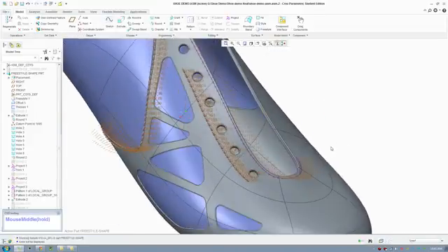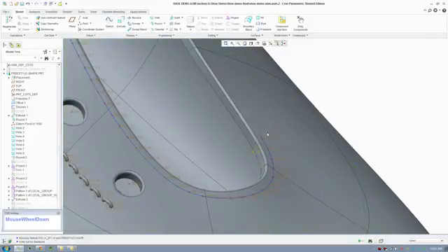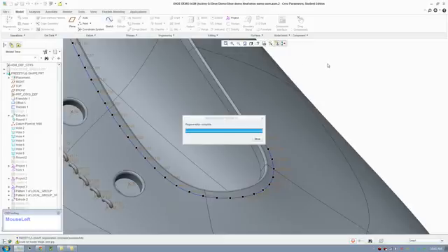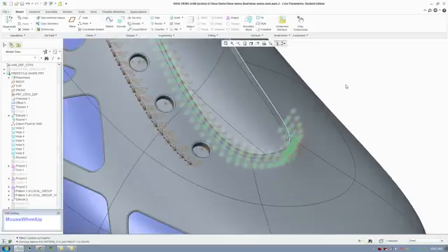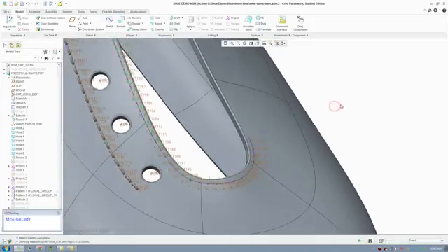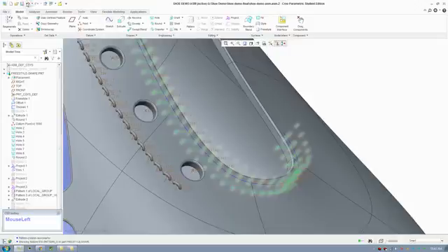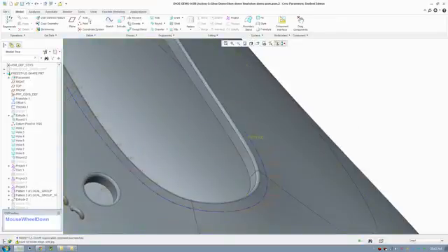Alright, since we have the base pattern, if you click pattern again, it recognizes the previous pattern. It's called reference patterning. So it applies that axis all the way across. Alright, I'm going to do one more axis. I'll actually just undo that so we can do all of that in one go later on. So we're going to do one more constraint.